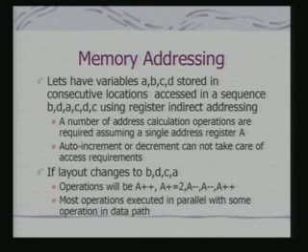So, that means I have to execute a separate instruction. If I could have used auto increment, that means I do not need a special instruction to do address calculation. If I do not use a special instruction for address calculation, it means I consume less time, I consume less energy.